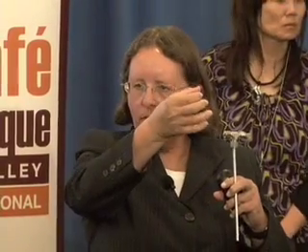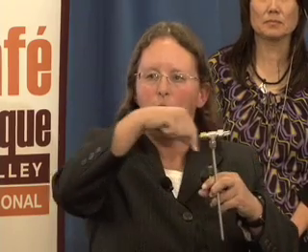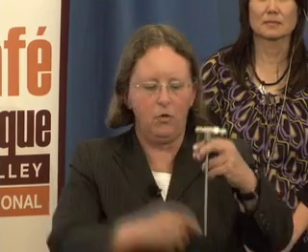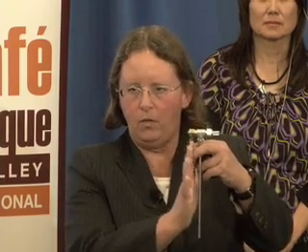And you can see it's basically just a metal tube, just hollow. The hole that we would drill in the slab is basically about that big. Then this gets dropped in, and then we grout it up so it's nice and tight, so that when we're taking a sample of the subslab soil gas, we make sure the air sample is coming from here. It's not coming up through the conduit, through the pathway here. And so that's just a soil gas probe.